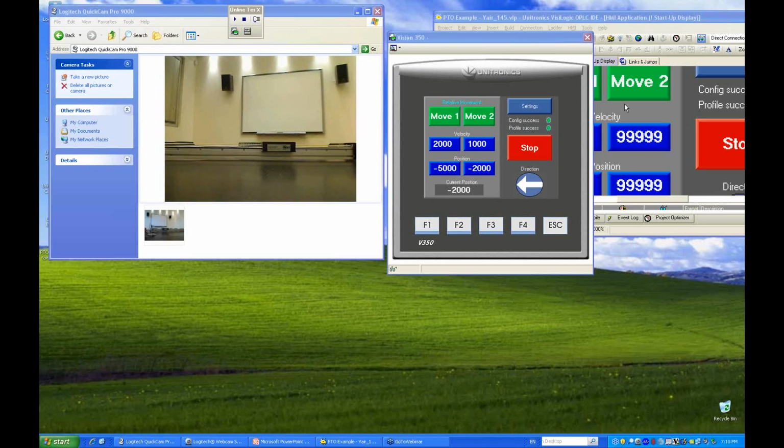You can change the speed during the movement with the PTO functionality. So you can take this speed from the PID loop, and the PID loop can take as an input the data from the encoder. So yes, this can be done, but not as a built-in function, but with a little help with the ladder.